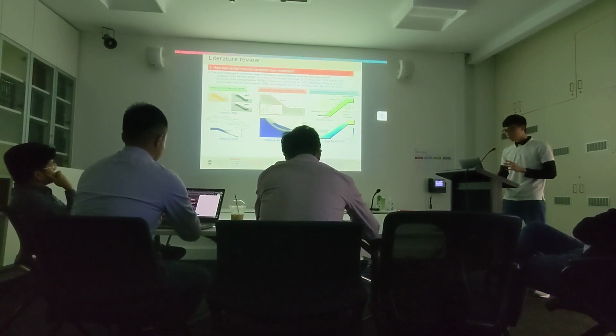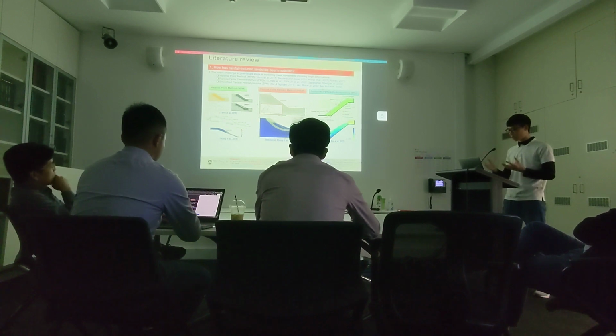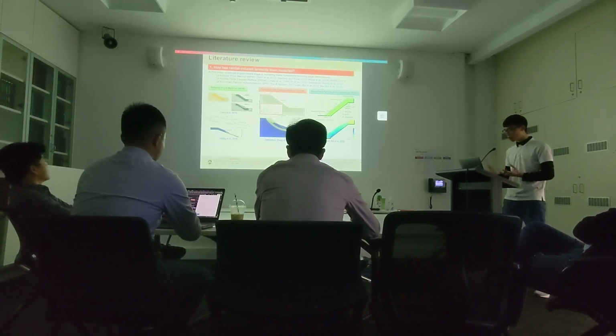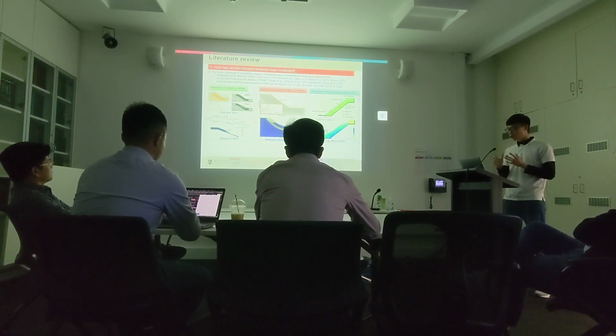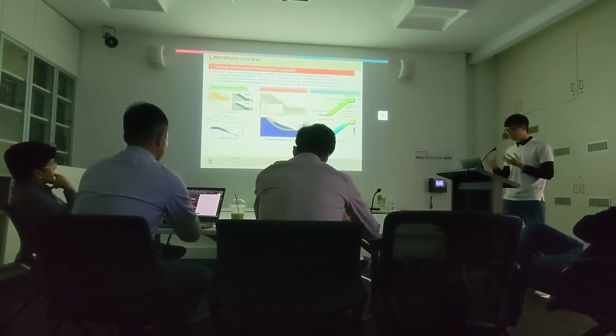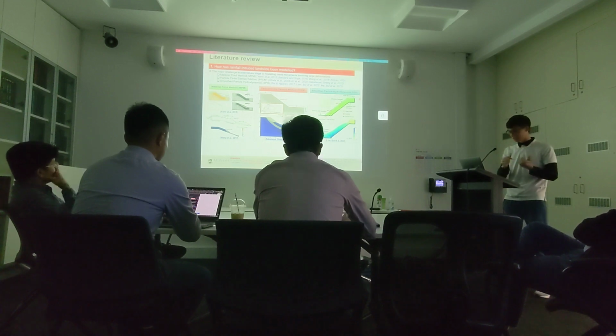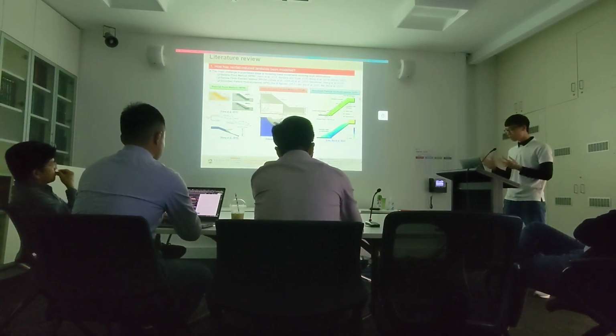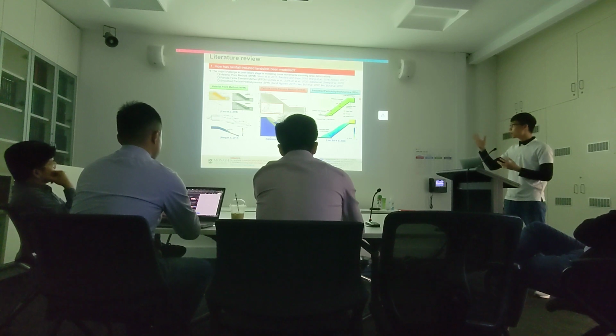It has been proved that the methods that you see over here have great capability in dealing with rainfall-induced landslides with large deformation. I also would like to emphasize here that each of the numerical tools has its own advantages and disadvantages. No method is better. For example, if I'm looking for safety design, I could definitely choose the finite element method in the previous slide. But if I'm looking at something with extremely large deformation, then I could have the option of MPM, PFEM, or HVX over here.